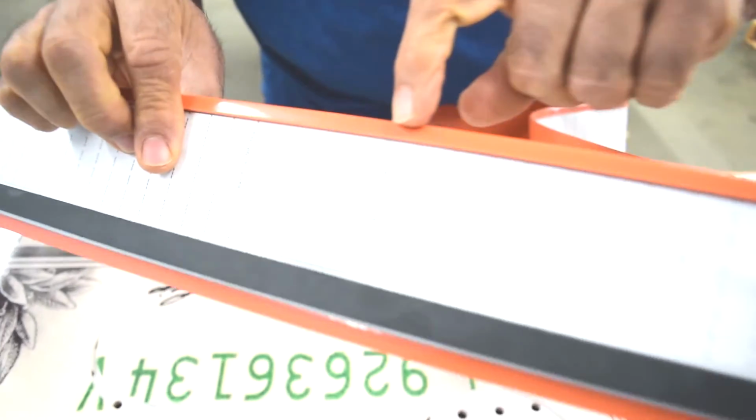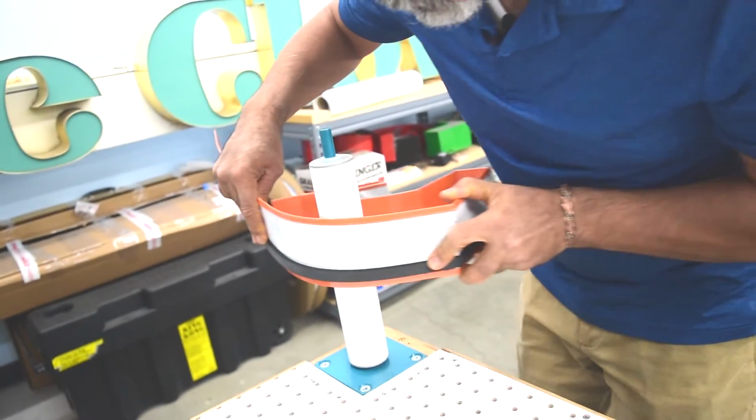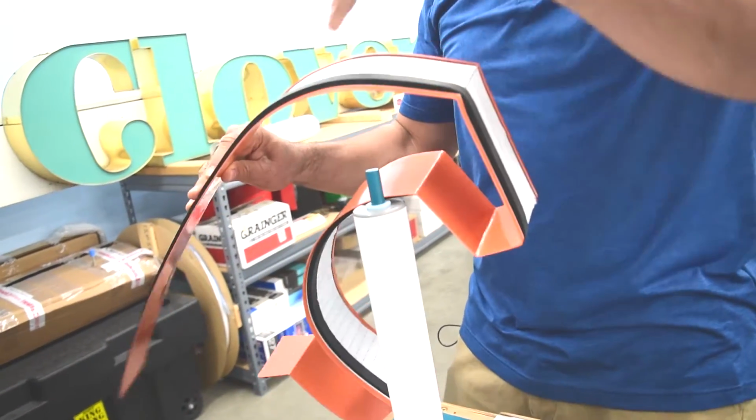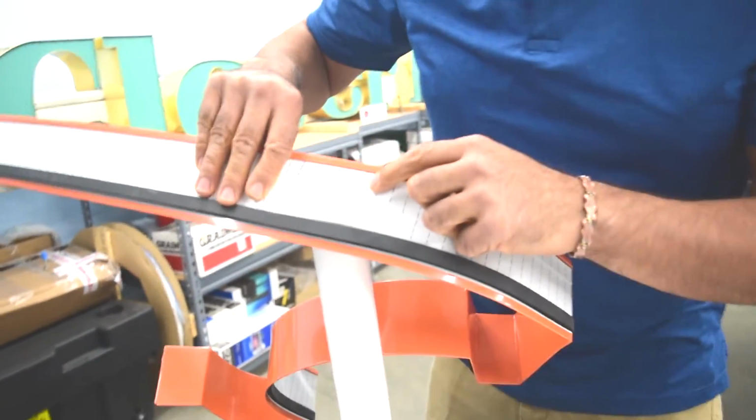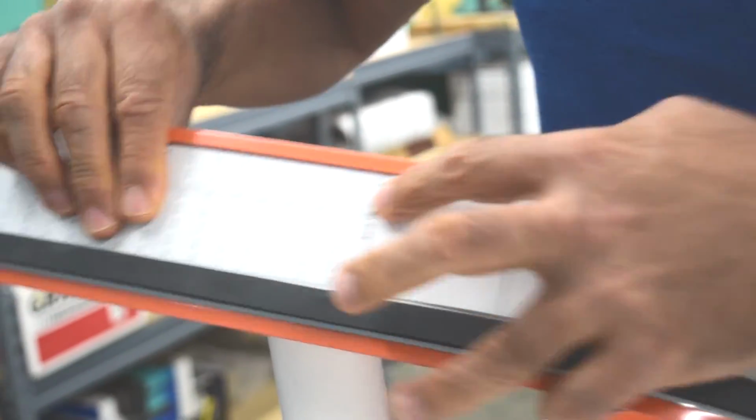This one is telling us to arc down. So from here to here is going to be an arc down. So we roll it downward. So it's arc down. We have a bend up, bend up. So we can flip it around, bend it up. And like I mentioned, it's called bend up because we're looking from the inside. It's bending in the upward direction.